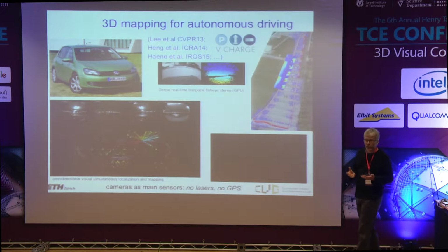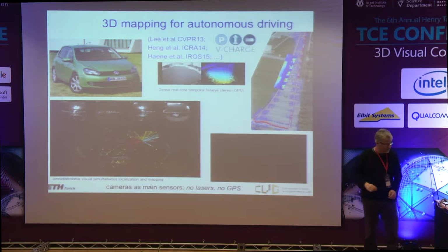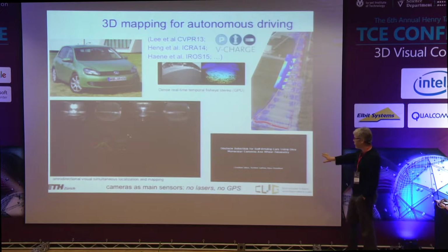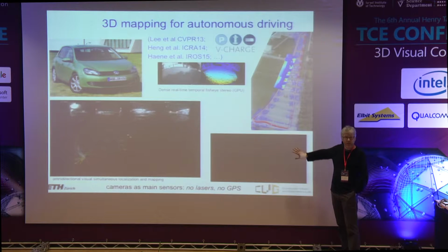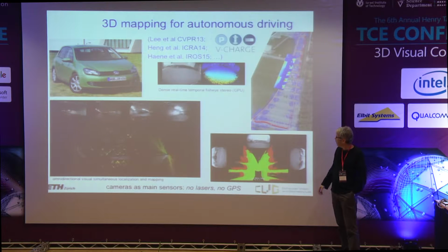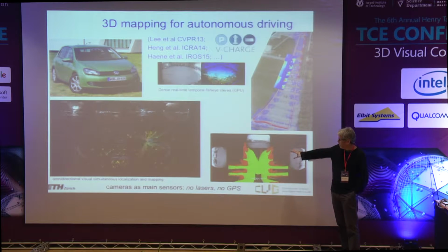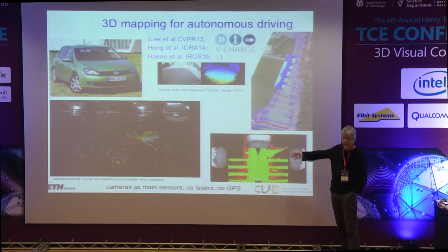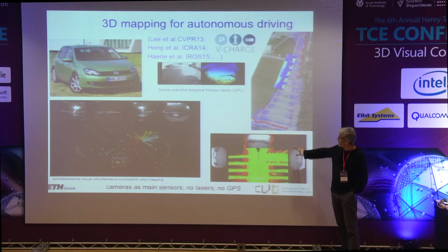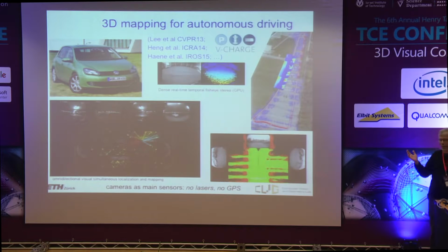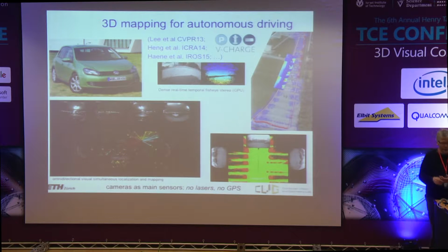Also, from the same fisheye imagery, we can very efficiently extract motion stereo and get depth maps. And then from those depth maps, essentially also get full obstacle maps, at least of the static parts of the world, all done very efficiently on GPUs, but also on essentially Tango tablet level. So NVIDIA K1, for example, does this in real time. And so we can get these types of maps. Of course, here also, as we heard earlier, it's very important if we could add semantics to this.